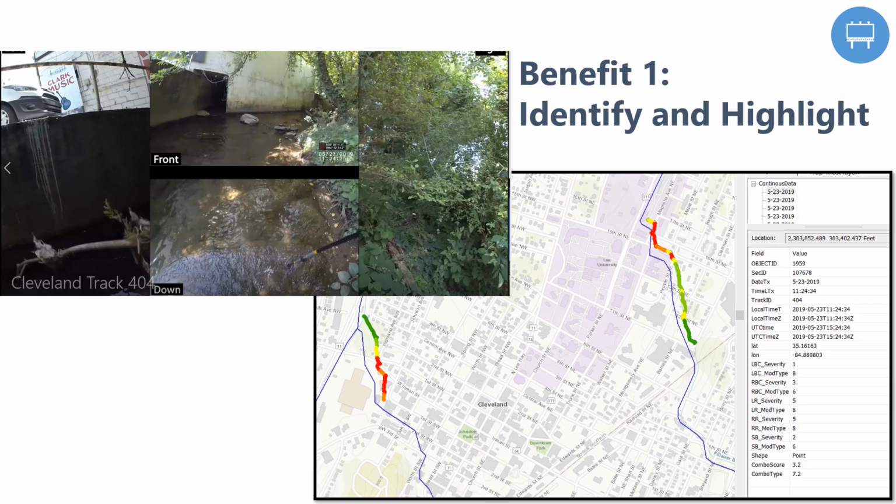An HDSS report contains easy-to-understand mapping and modeling outputs that are directly tied to the stream view video output. Every single HDSS data point is associated with a second of video, the associated GPS coordinates, plot data, and video on a continuous survey track log. A closer inspection of the data would reveal individual severity and condition scores for both bank conditions, both riparian zones, and the stream bed.